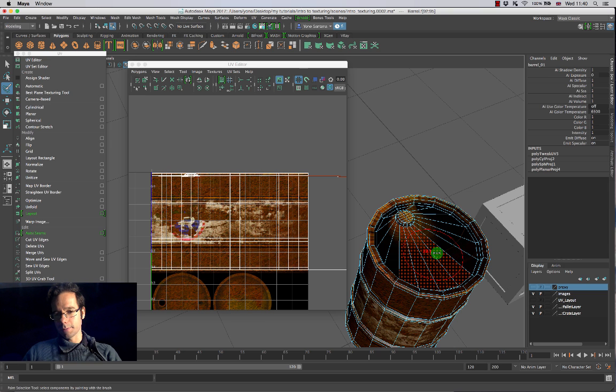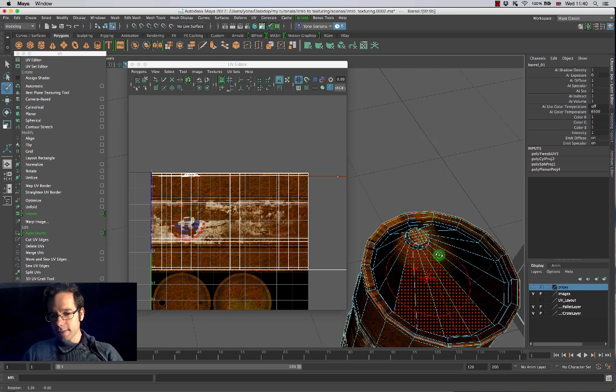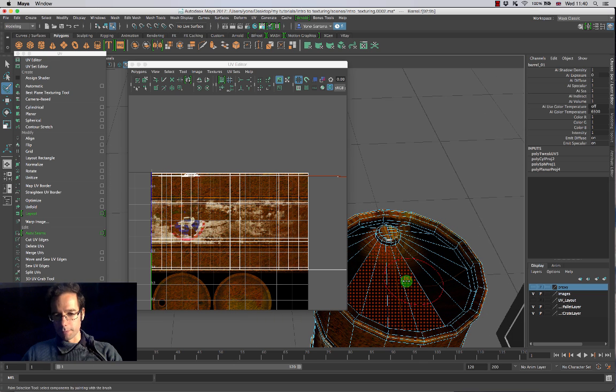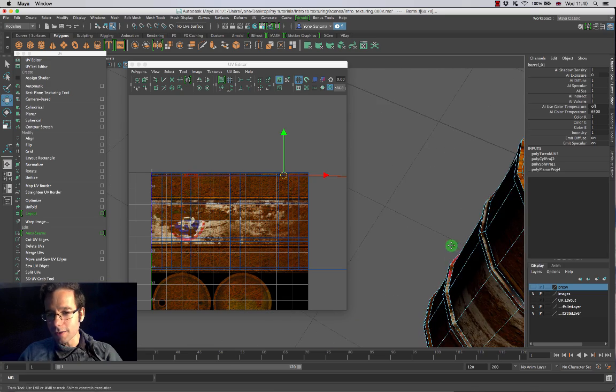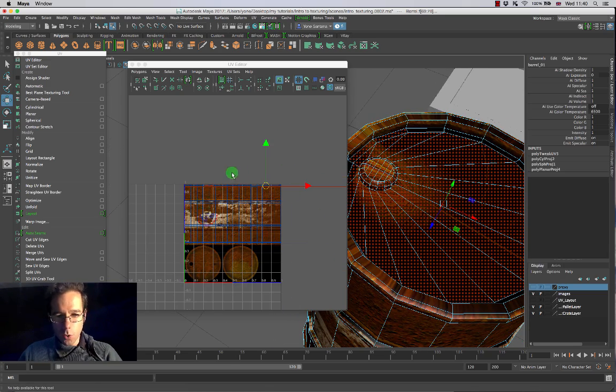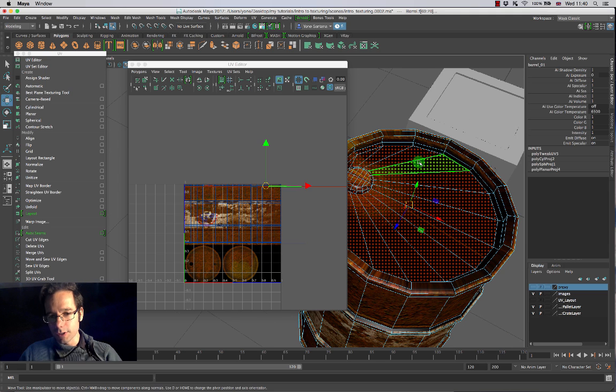And again, it's left click and mouse button click and drag. This brush, I'm just going to make a little bit smaller, will select any polygon faces that I drag my mouse on top of. So literally I can paint in a selection just like that. If I paint too much, I can use any of the selection tools, or press, can I press Alt and Shift? See, will that select it there? No, it won't. So I'm just going to go back to my traditional selection tool and deselect those faces like so. Okay, so I've now selected all of the faces at the top over here.